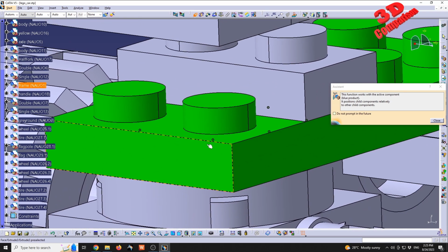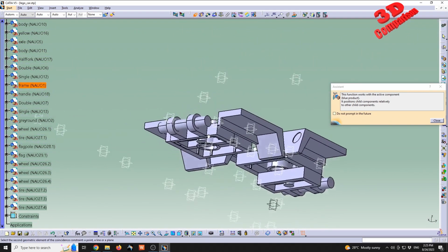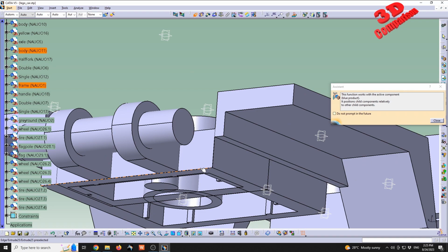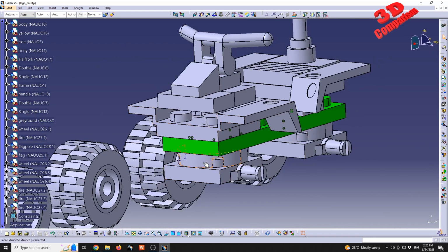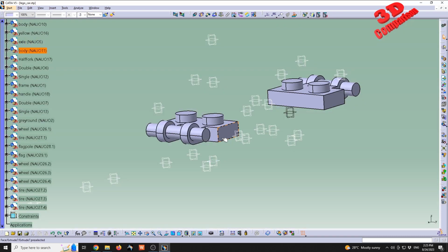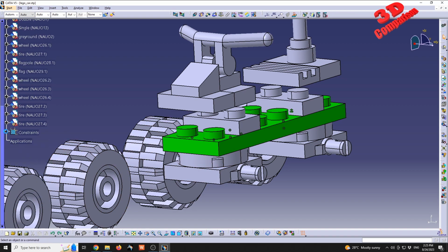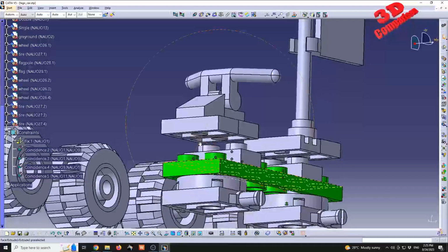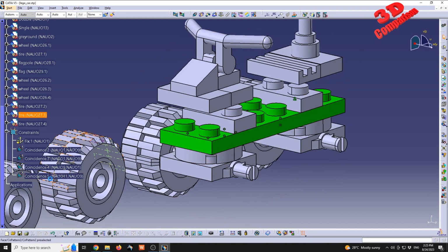If you're not getting the exact desired selection, you're going to get a plane. You can zoom in and then you can select that desired element. And we know that that edge should be coincident with this one. And now if I send that back, okay, let me undo that because I hid multiple parts. I press undo. And if you also misalign some of the parts, you can always undo. You can check the last coincidence. We see that now coincidence 5 is the last one.